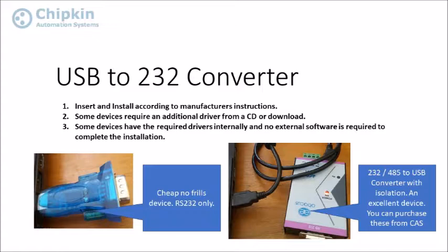It's a great converter. There are lots of cheap no-frills devices like the one I'm showing on the left there. That one's RS232 only. Some of them need additional software when you install them. It's a bit of a pain, but that's the way it is. When you install one of these devices, you never know what COM port it's going to be assigned to, and that can be the one that'll hiccup.